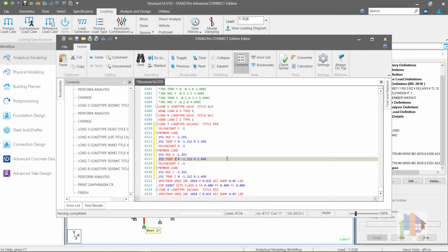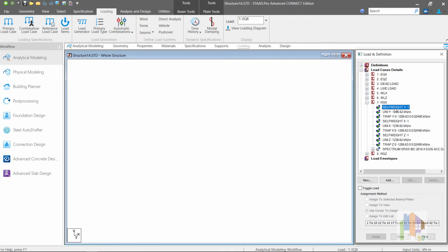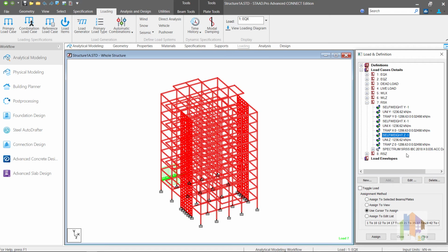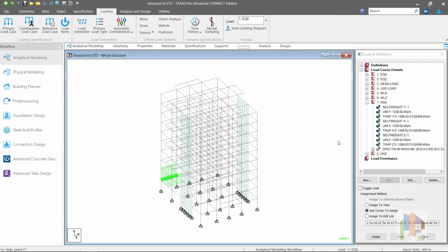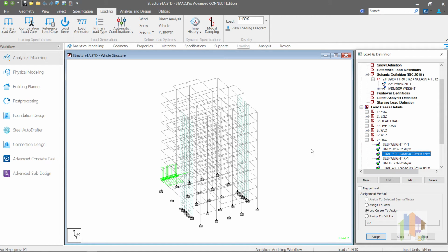Also note that it is better to change the load sign from minus to plus as this is only the weight. I have done this for a few load items. Now consider doing the same with all the load items from dead load and live load cases. Well, this is a duplication of job, right? You need to define gravity loads under primary load case, then once again define that as seismic weight for the static seismic analysis, and finally define the same load in three directions for mass modeling for dynamic analysis. The same load is defined thrice, which is not at all user friendly.